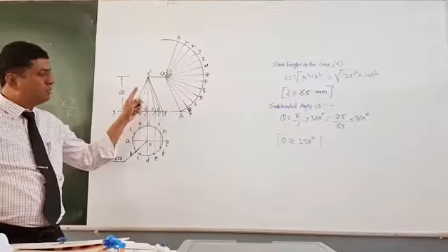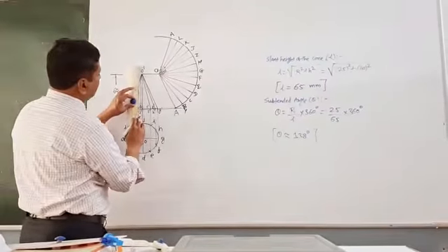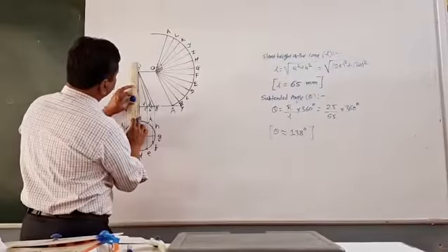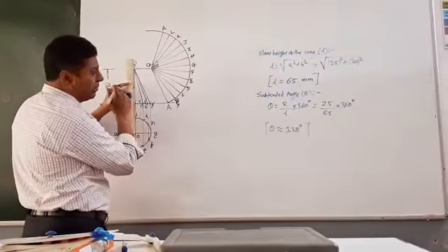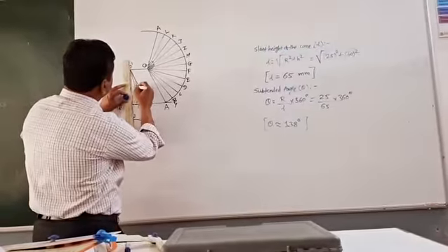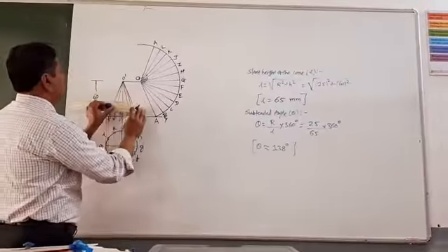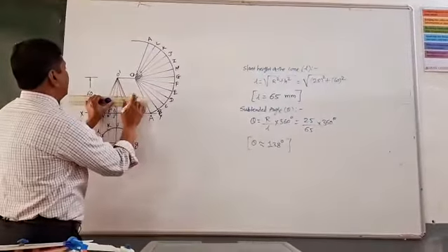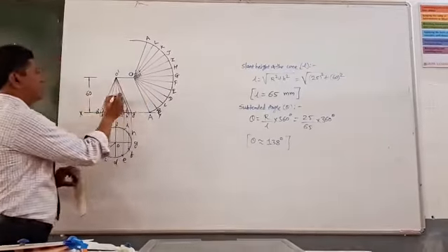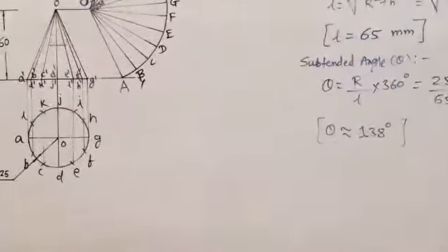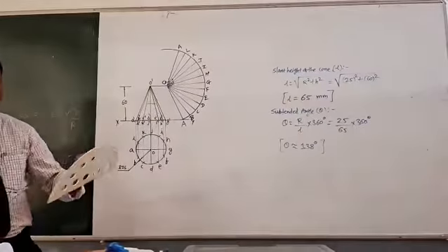First, we have to mark the midpoint of the axis. The total length of the axis is 60. What is the midpoint? The midpoint is at 30 mm. Okay. So mark this point, and from that midpoint draw one small horizontal line. Then take the angle protector.